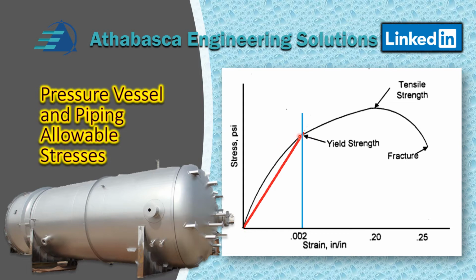And basically the yield is defined as a 0.002 inches per inch offset, okay? And that's a definition of a yield. This yield stress is a key issue when determining allowable stresses, and the tensile stress shown here.